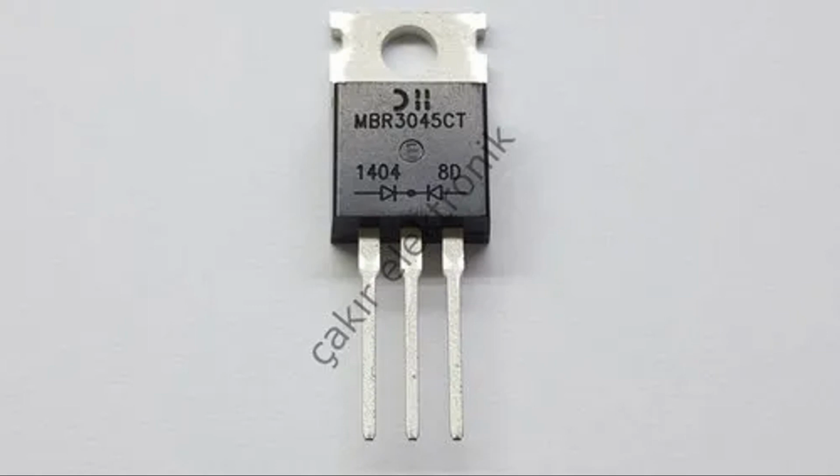Switching circuits process digital signals that have two discrete levels: logic 0, low voltage level, and logic 1, high voltage level. These binary signals represent the basic units of information in digital systems. Boolean algebra. The behavior of switching circuits is based on Boolean algebra, a mathematical system that represents logical operations using algebraic expressions. Boolean algebra provides the foundation for designing and analyzing digital logic circuits.